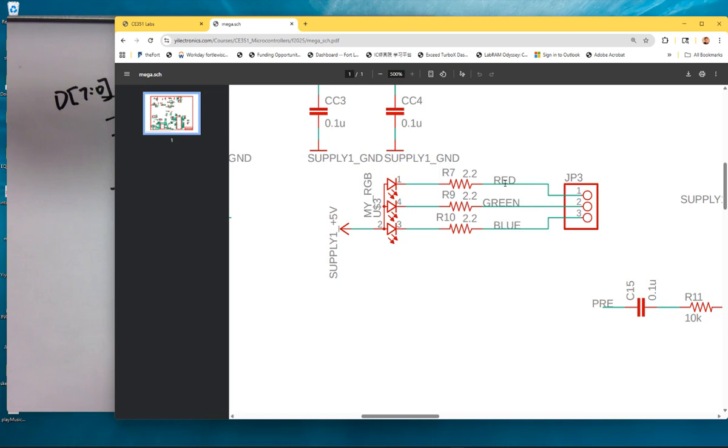Because you only need to control one terminal of it in order to turn it on and off, right? So you don't have to leave both terminals open. You know what I mean? So it's just a short of one side of all the LEDs to 5 volts for all of them, and you just toggle one side, just toggle the cathode over here.